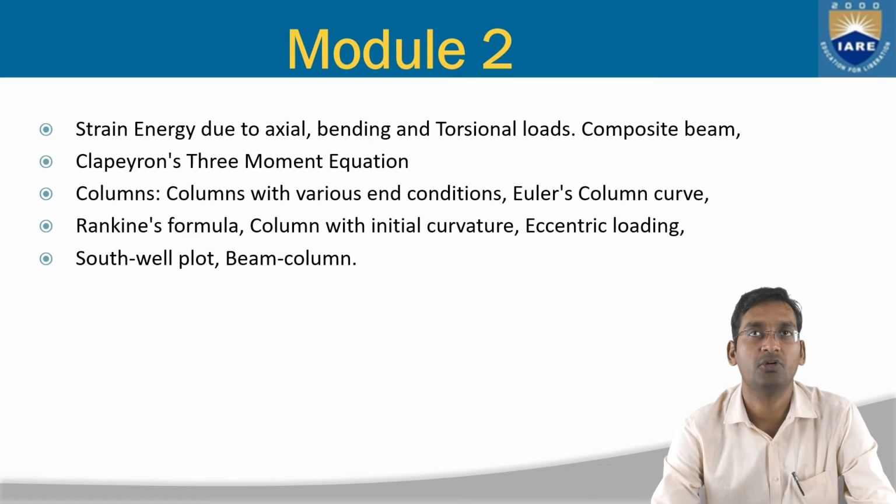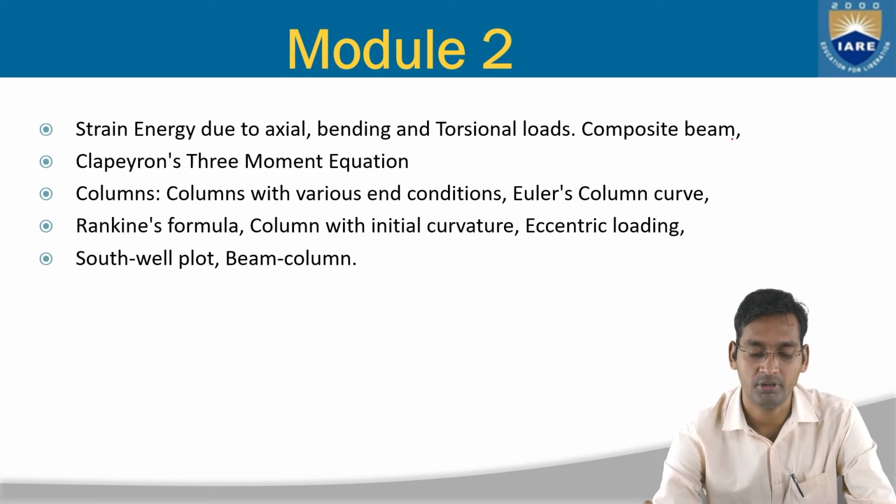Next, it's the Clapeyron three-moment equation. So by taking the three moments, how to solve the same by the energy method, but it's given by Clapeyron. So the Clapeyron three-moment method, how to solve the numericals, that the student will see.